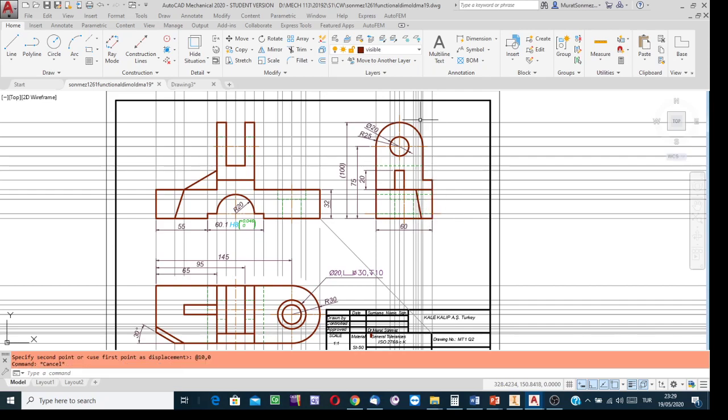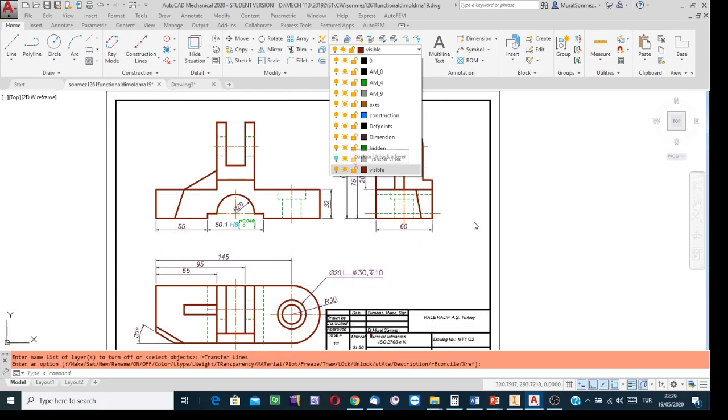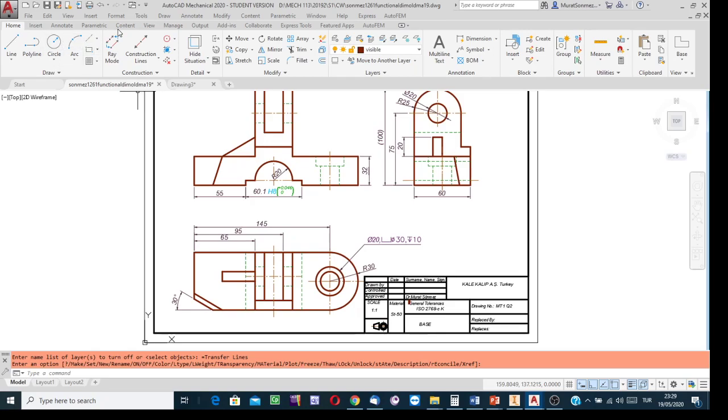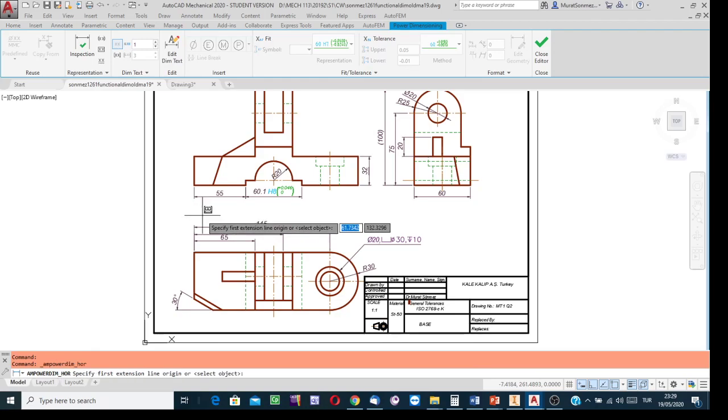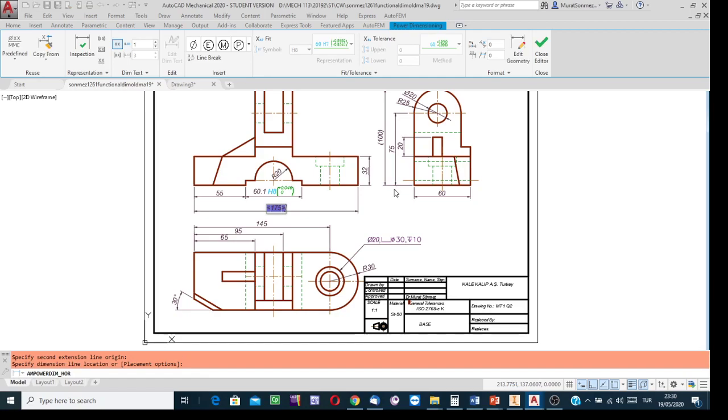So on and so forth. And then turn off the visibility of the transfer lines, and then you see, having managed to get more space, show the total width. Annotation, width value from here to there, show the dimension. But here this dimension, similar to the height, is a reference dimension. Why? Because 145 plus 30 is equal to the overall width.